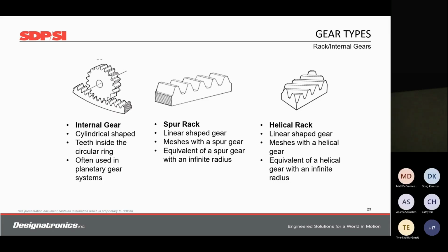Another type of gear that requires very accurate machining methods is the spur rack. The spur rack requires a very accurate straightness at the base because special attention has to be given to the entire length of the part, because tolerance adds up inch per inch or millimeter per millimeter. An example of this, say you're trying to make an AGMA 10 spur rack. An example call out for the base is 2/10 of inch to inch straightness. At 10 inches, this can amount to 0.002 inches of height variation, which can cause interference with the mating gear, meaning it won't let the mating gear rotate.